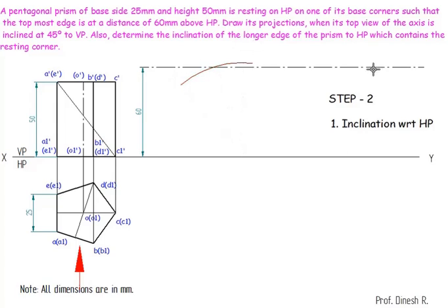So here I can cut this at 2 points. Even you can keep it here or else you can keep it here. Both are correct. So if you refer to any books with respect to this, they have kept it here. It is not wrong if you're going to keep it here. Finally we need to keep this edge at the height of 60 mm. Now I got this point. I am going to find this distance from here to here, which is at the distance of 38.47.